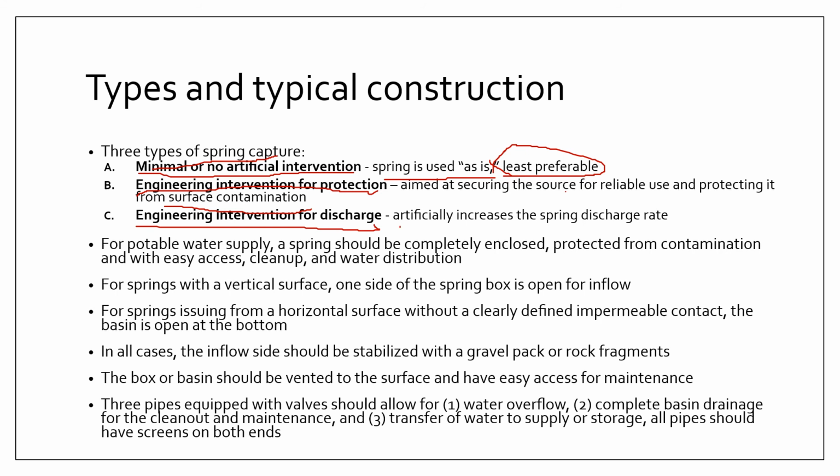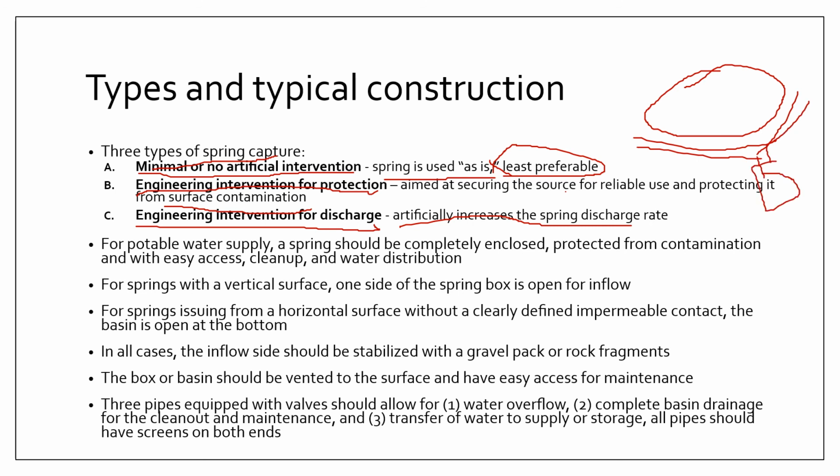All right, so this involves constructing collector trenches. So this will typically involve digging around the area of the seepage and creating a channel to ensure that the whole seepage area is actually collected and concentrated on a single spring box. All right, so your seepage is typically trenched. You typically dig a trench around the seepage, and then you divert all the seepage into a central spring box.